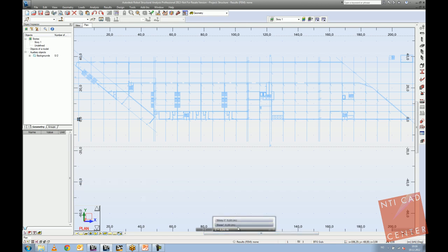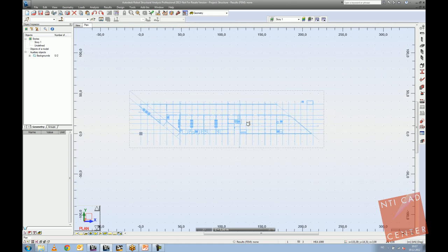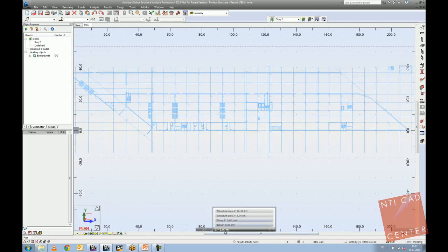But if you have grids, then you have the possibility to utilize all of the grids automatically. So if I go here, for example, and say in the Z direction I don't want to use any stories, I will use grids from 0, every, for example, 3 floors. Every one of the floors should be 4 meters high. Saying add, apply and close. Of course, I should have X and Y direction grids, but let's say I'm just doing it plain simple now, adding just the Z direction.